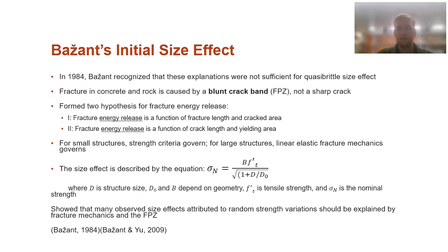And what he noticed was from this graph that we saw on the previous slide, I'll flash back to it real quick because I think it's important. Oh, just kidding, I can't go back a slide. But essentially we saw that there was this plateau that's governed by the strength criterion, and then as soon as you translate to larger structures, it starts to follow the linear elastic fracture mechanics route.